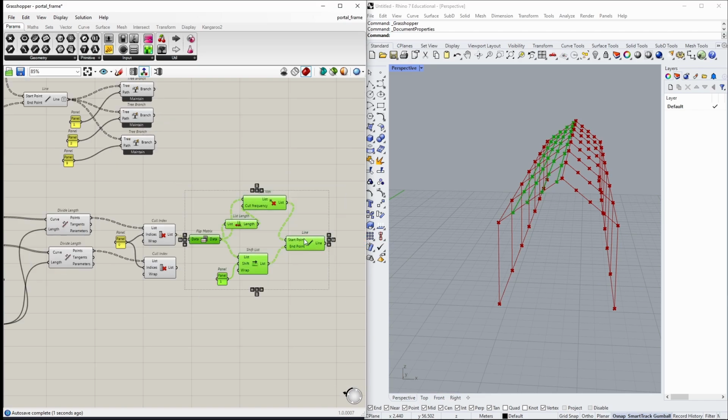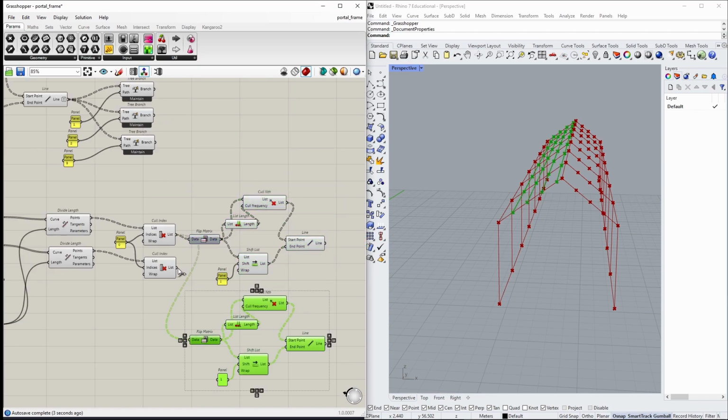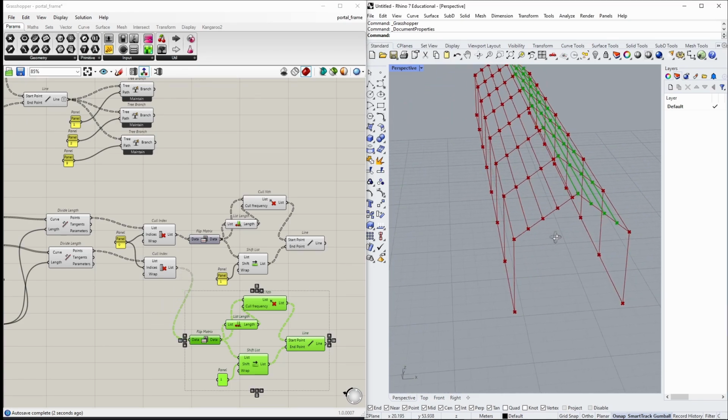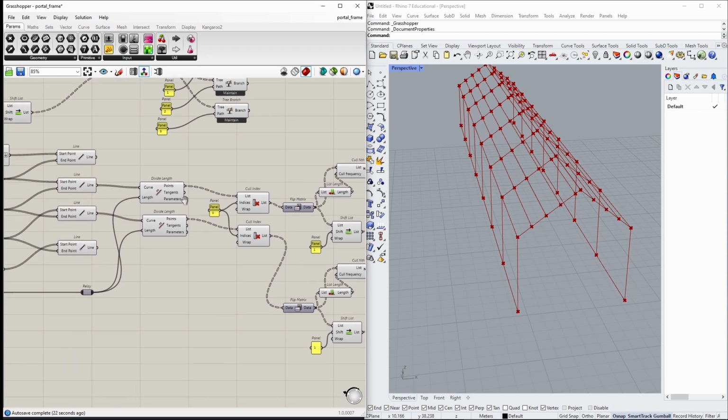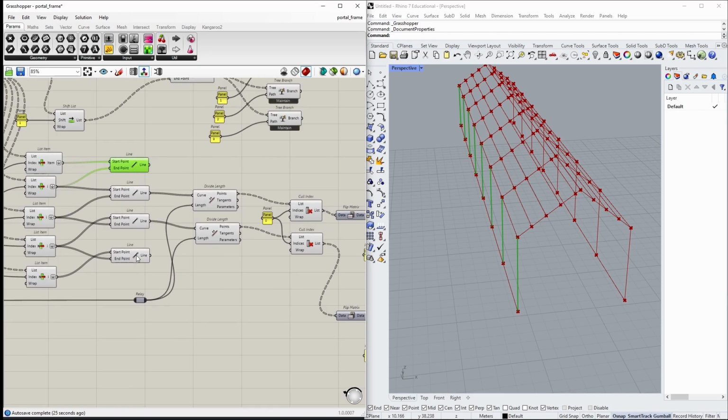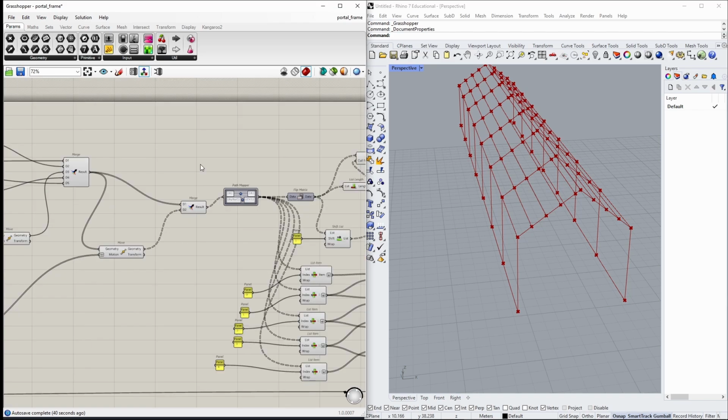Copy this by holding down the Alt key. And we got our purlins. This process is the same on the sides. You can do that by taking the 0, 1 and the 3, 4 lines, this, and do that flipping thing again. At this point, we are finished.